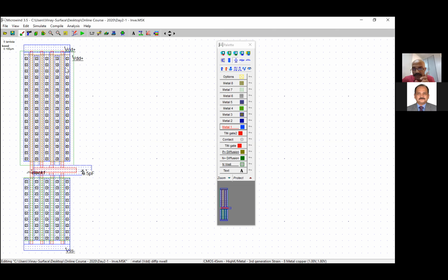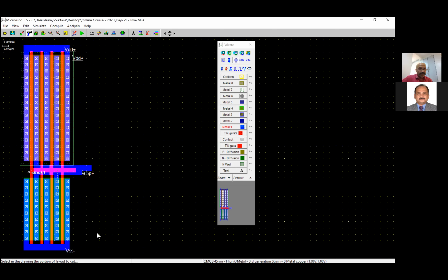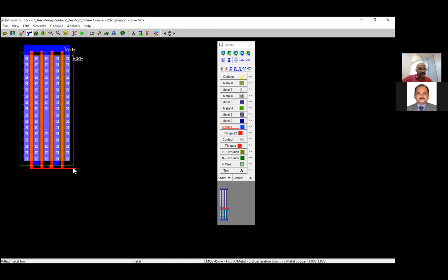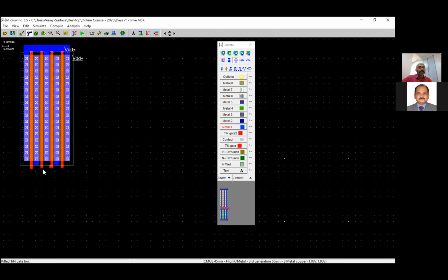And you remember the quiescent point, what did I ask? Close to 0.25. I want something closer to 0.25, so it should be pulled down towards the lower side, down to 0.25. So what I do, I just remove the NMOS side. I just remove the part of the NMOS, I just delete the NMOS transistor, and I remake the NMOS transistor.